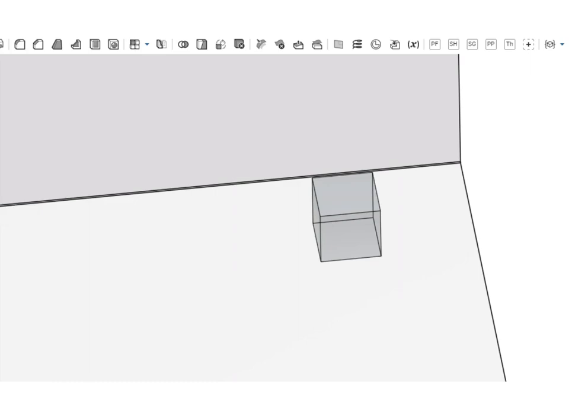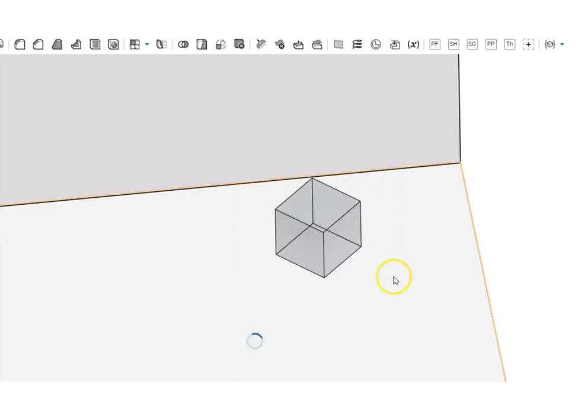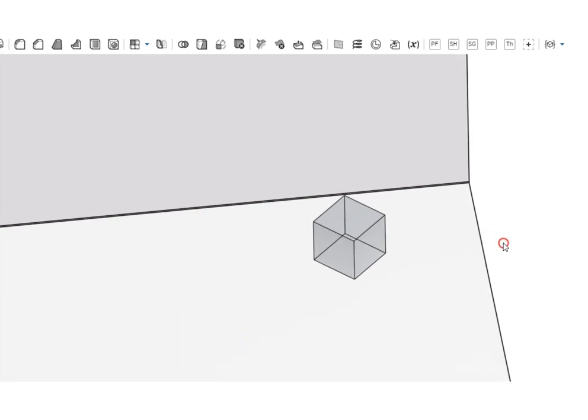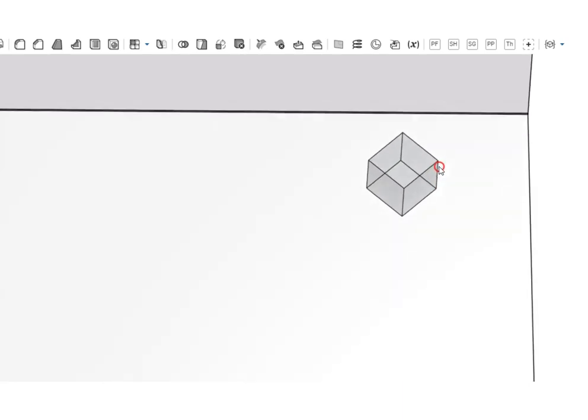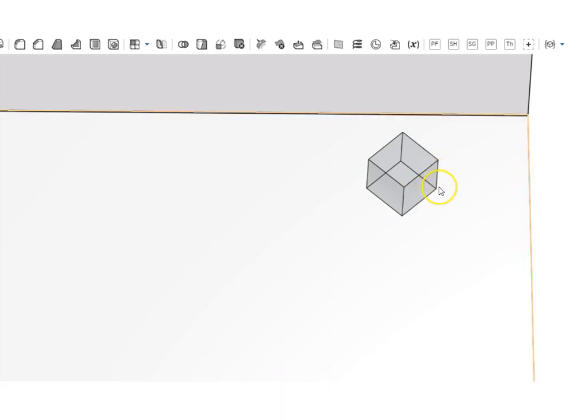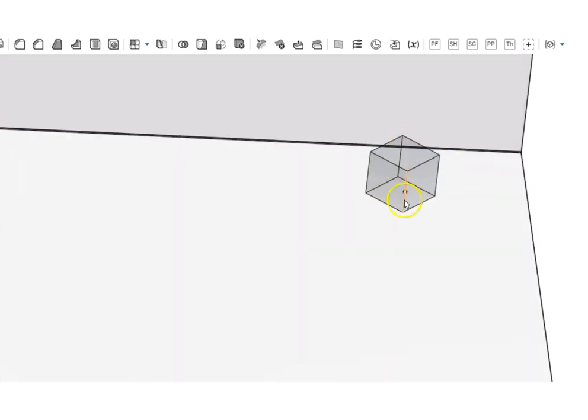Now we could see that if you look from the top, the cube has been rotated 45 degrees, so that when we look here, we get a corner here. Instead of a face, instead of a base edge, now there is a corner, so that in the next step, when we try to tilt it, we have a corner suitably positioned. With respect to this, you can easily tilt this solid in the next step.